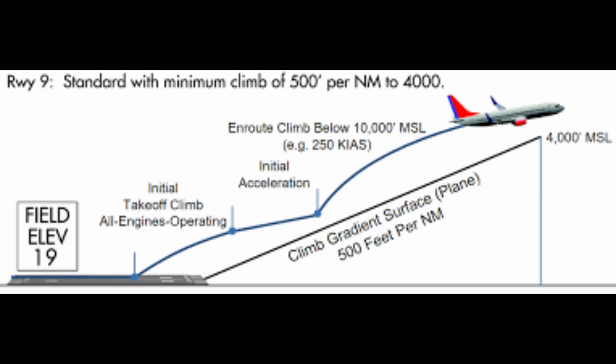Generally, TOD is used in airplanes with an FMS and represents the point at which descent is first initiated from cruise altitude. FMS also assists in level flight by cruising at the most fuel-saving speed, providing continuing guidance along the flight plan route including great circle direct routes, and continuous evaluation and prediction of fuel consumption along with changing clearance data.